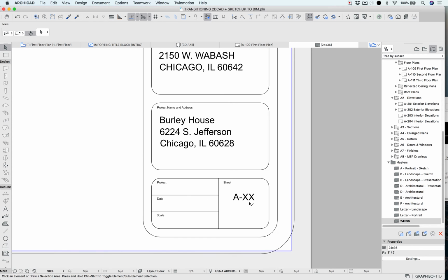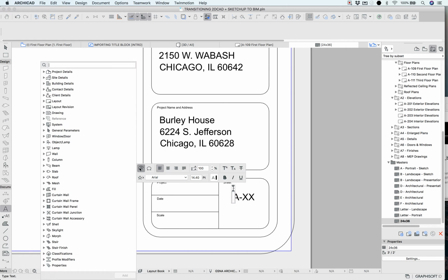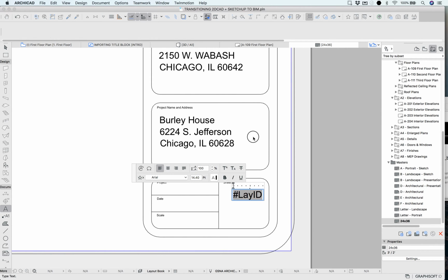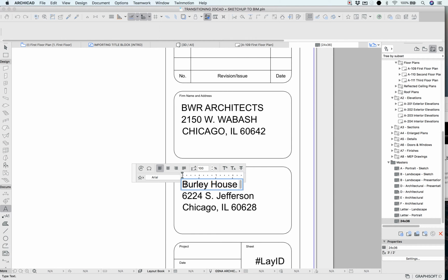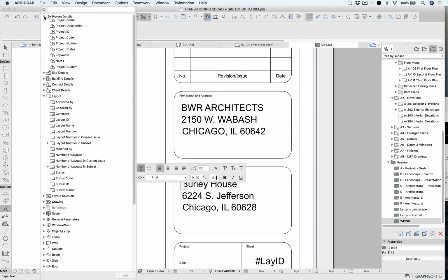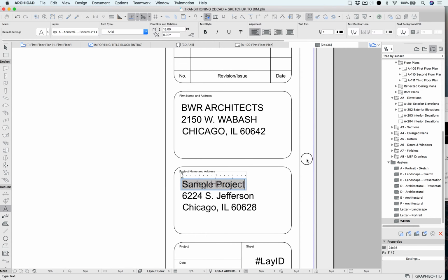So one thing we want to do just to get started, once again talking about the auto text, the automation of our set, is to handle places where there are small changes and we have room for error. Instead of typing a page number, we can label it automatically, using things like auto text so that when there is a change in my layout, that stuff can update properly. So when you do bring in your title block, you do want to take out some of the typed information, just plain type text, and then enter in information like project name, ID, address, client information, etc.